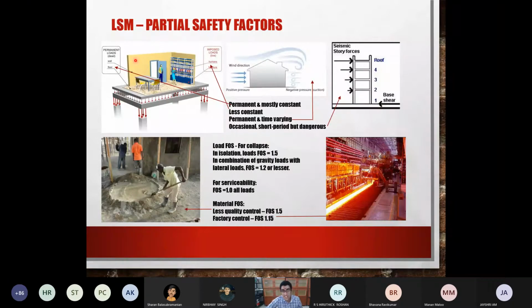But that's not the only load. With very tall buildings, you also have the issue of wind. If you have, say, 5-6 story buildings, then you cannot just base your design on the dead and live loads. Wind also causes a heavy load. Okay, wind is not a joke. Wind can actually generate quite a lot of force.